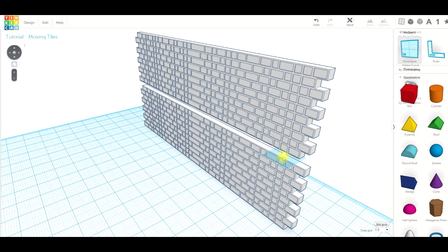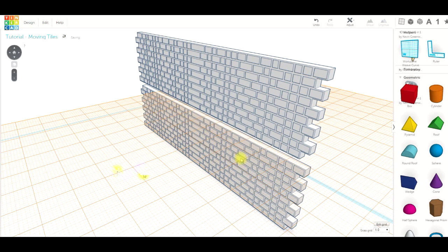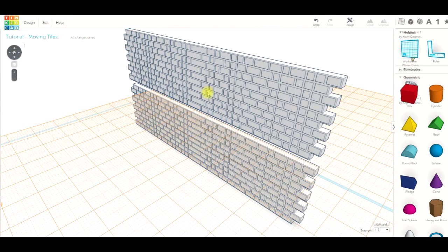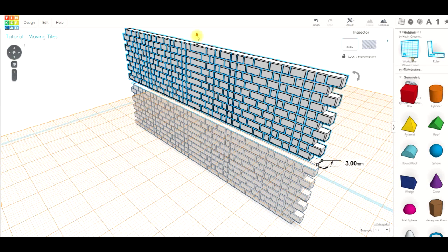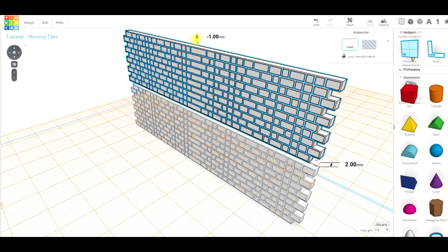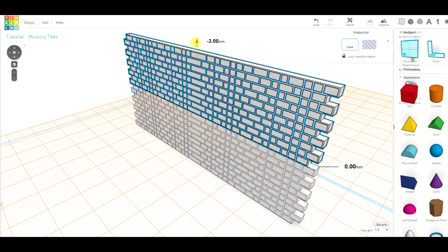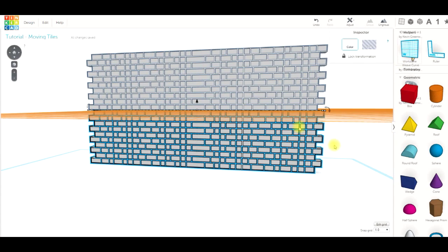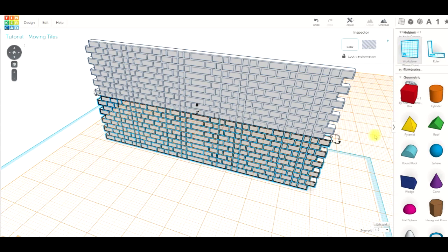If I want to be absolutely 100% precise, you remember this little square grid, and this is what we're going through in this tutorial. Click the grid, drop it on top of that piece there, and set the grid right across the top of that piece. Okay, click the second 4, hover over it, and you can see on the bottom right hand corner that we're 3mm from that grid.